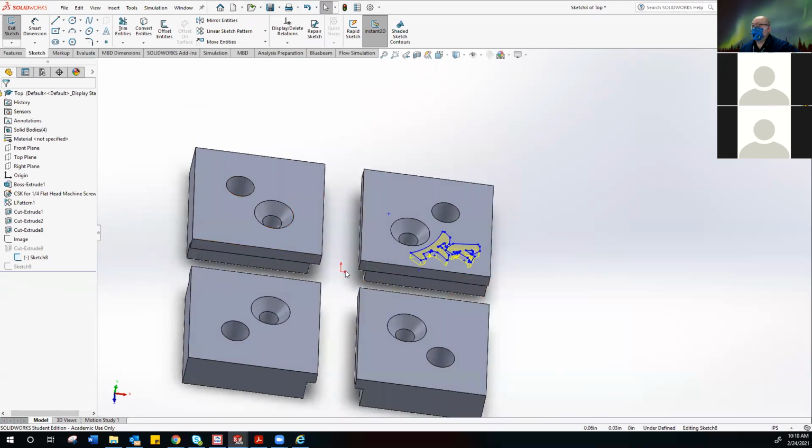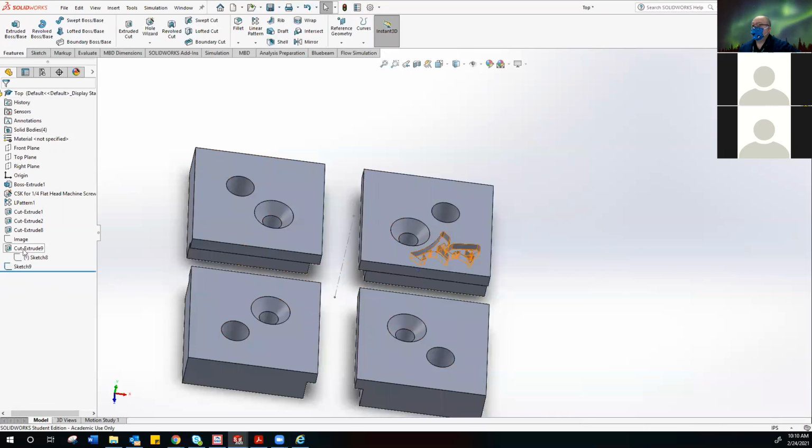And I do not have a center point here. My center line doesn't show. I need that center line really, really badly right now. And it's happening in the future of this, right? So how do we get it to go in the past? I'm going to have to exit my sketch for a minute, take the sketch that has the axis line, hold my left button down on it, we did this the other day, and slide it up before my initials.